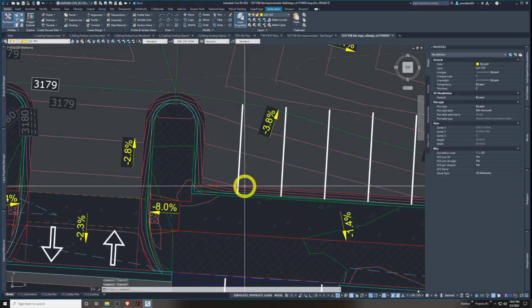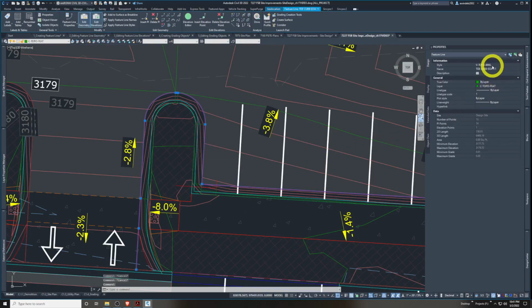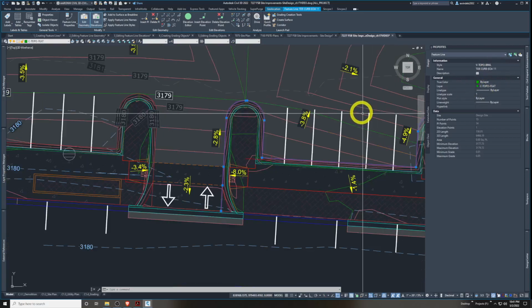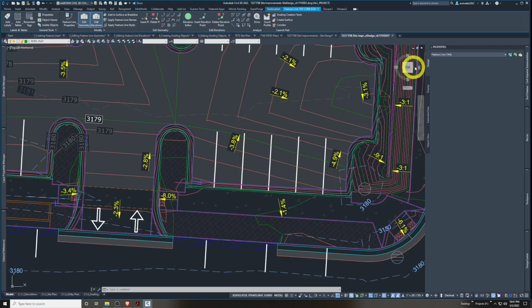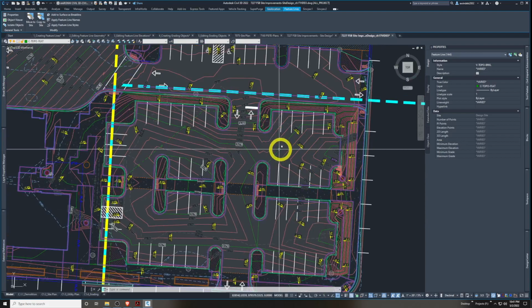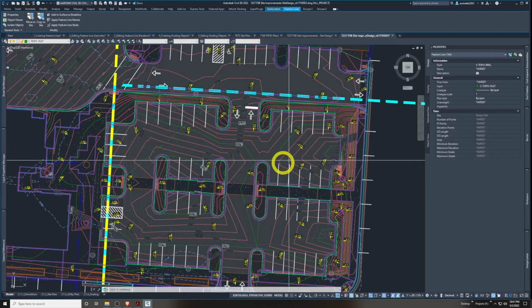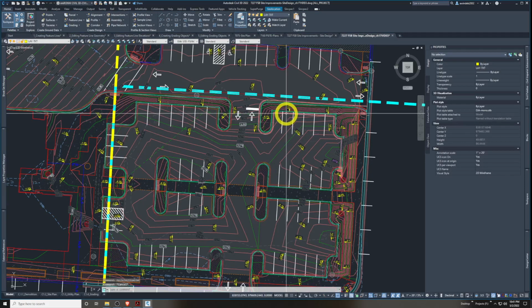But beyond that, I have a pile of feature lines I put on a certain style here, and they're mostly just on V-topo break line. I have them named a certain thing, and they're on their given layer. If I right click and say select similar, I have about 144 of them, so quite a few. And a lot of them I graded out the front of the curbs first, okay? So I have them very set horizontally and vertically, which took some time.